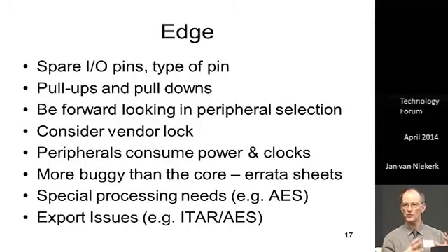And so some of the things that I've learned in my experience, some of the key things I'm putting down here. Obviously, depending on how many things you want to do, how many pins you need to wiggle, when you select a microcontroller, consider how many. Don't just go buy a microcontroller that if you want to toggle 4 things has 4 pins on it.